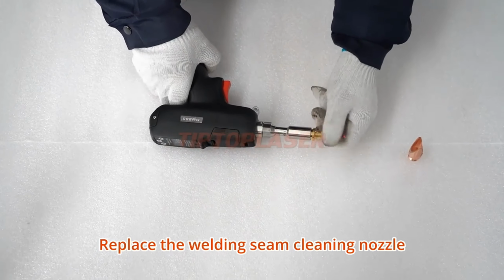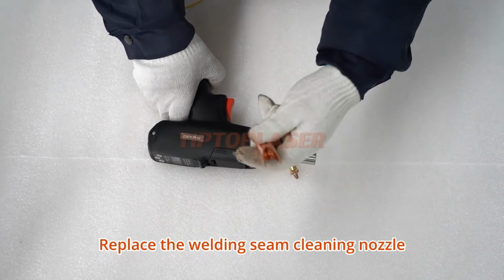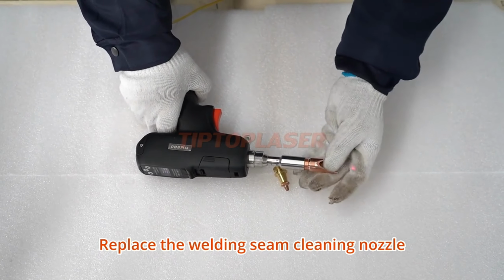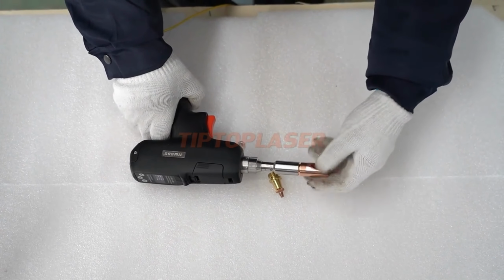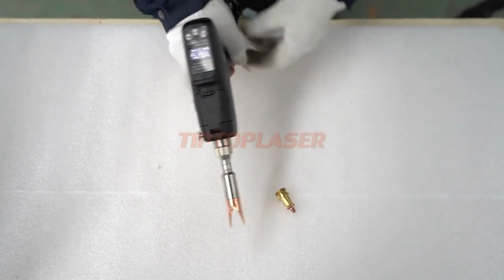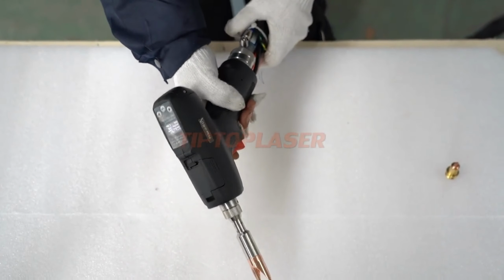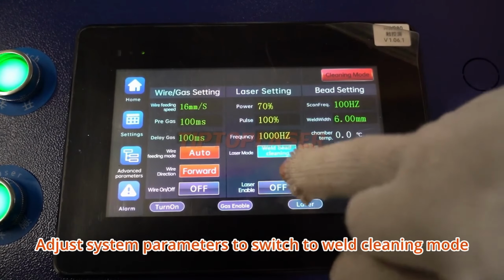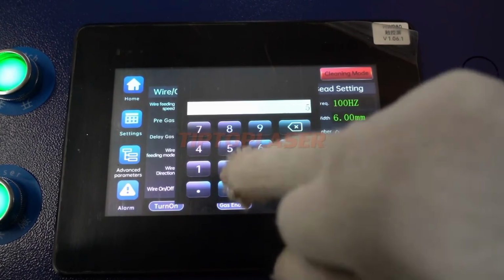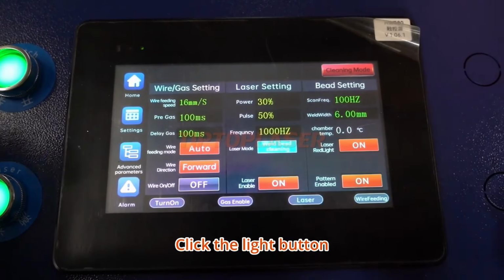Replace the welding seam cleaning nozzle. Adjust system parameters to switch to weld cleaning mode. 30% power. Frequency 50%. Click the light button.